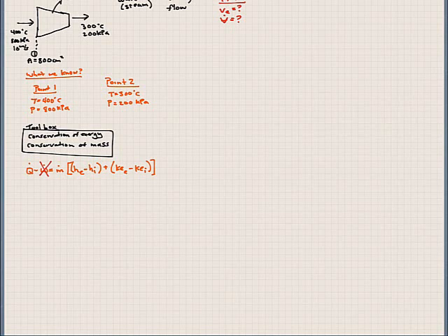Okay, so we have heat transfer. And heat transfer out of a system, when we use our typical sign convention, is going to be negative. So we have negative 25,000 kilowatts, or watts, I'm sorry. Now, keep in mind, I'm writing watts because I have this little dot. Q dot signifies that it's a rate, okay? So it's going to be per unit time.